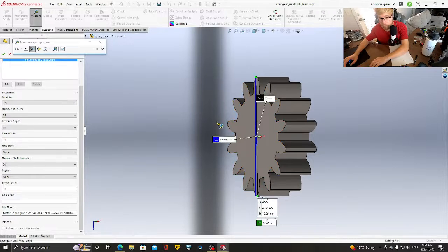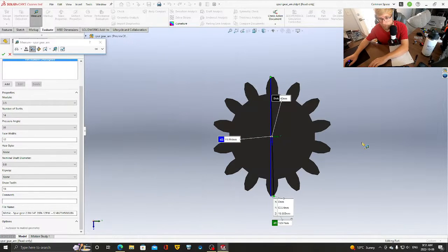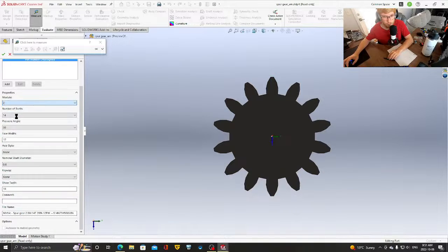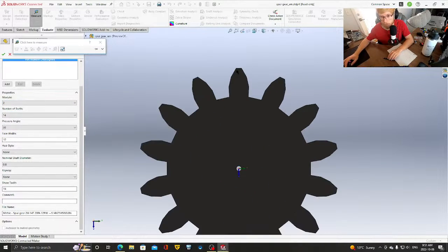How wide are you? You are going to be 40 mil across, so it'll be 20 halfway. We have a 64 mil gap, so it'll be 80 total. These gears are just going to interface in the middle, so I really only have to have them halfway. 20 either side should be fine, but I think I want to go a little smaller. So maybe decrease the module. If we go to 2, how wide are you now?